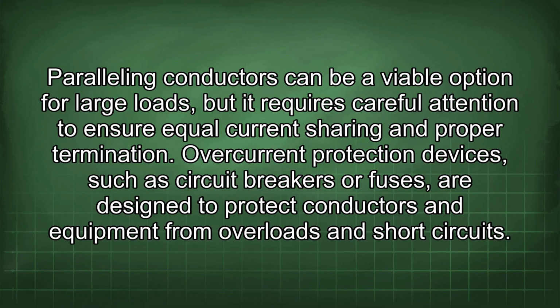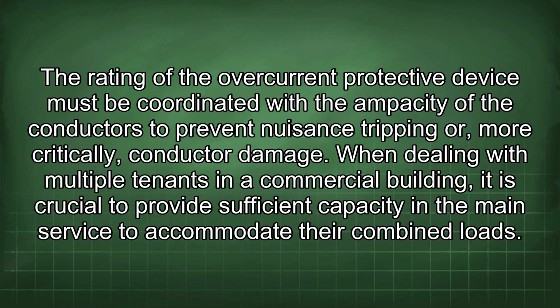Overcurrent protection devices, such as circuit breakers or fuses, are designed to protect conductors and equipment from overloads and short circuits. The rating of the overcurrent protective device must be coordinated with the ampacity of the conductors to prevent nuisance tripping or, more critically, conductor damage.